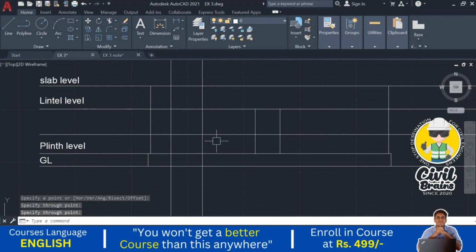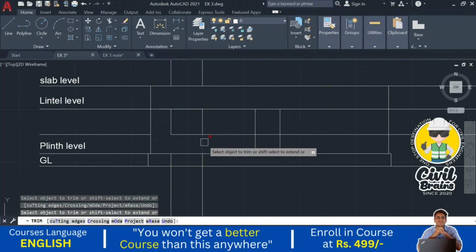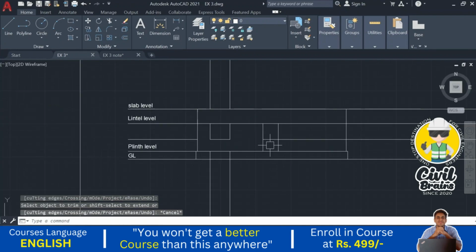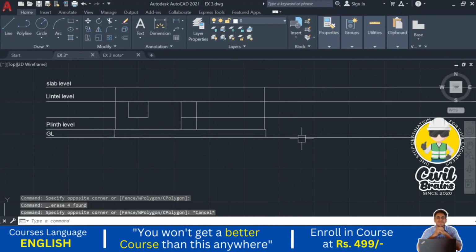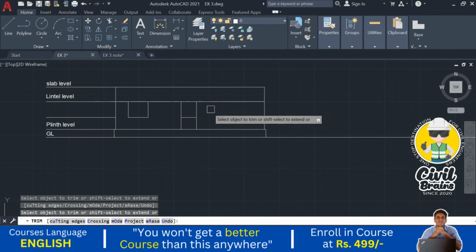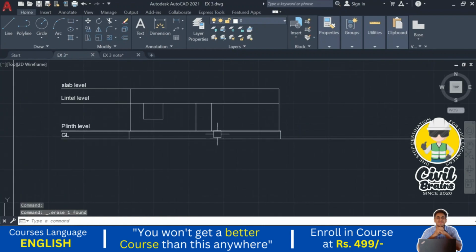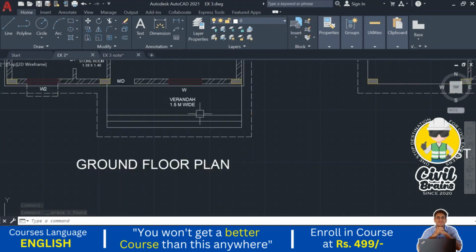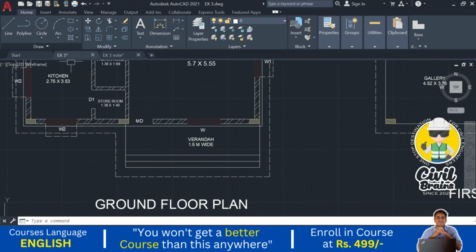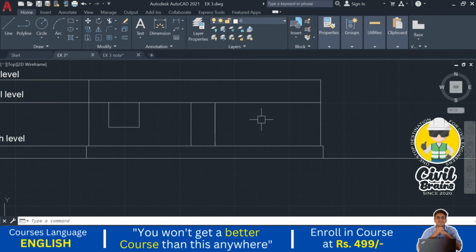Okay, here our W2, I just trim. Okay, so extra parts I just delete. So lintel level should be there only, we want that one. Okay, so this is our W2. Next, what is our W1? Oh, sorry, W. Again, sill level I just draw first, that is 1.6 meter, the depth of the W, and